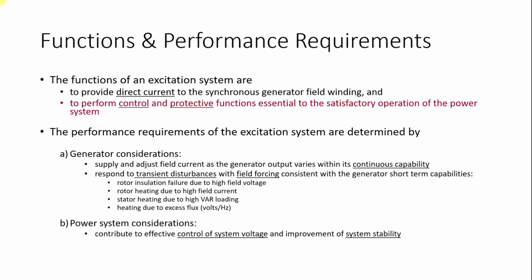But in dynamics, what happens when you have zero voltage on the terminal? When you have zero voltage on the terminal, the exciter is going to provide its maximum current to the rotor, and with this maximum current being provided to the rotor, a huge flux is going to be generated, which is going to be the Q max value. A higher Q max value is going to be generated into the system.